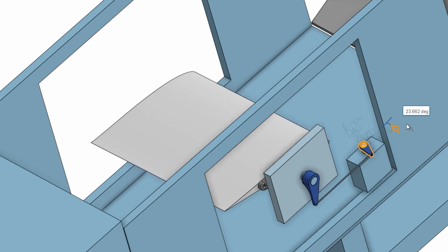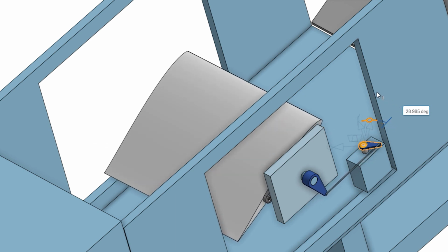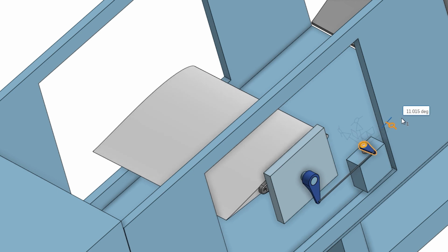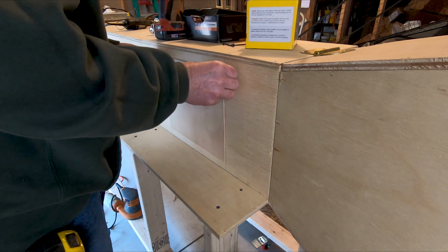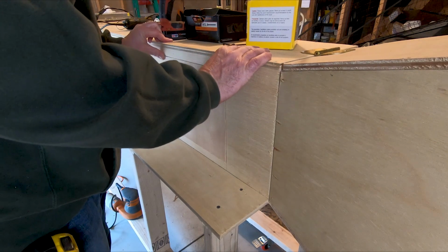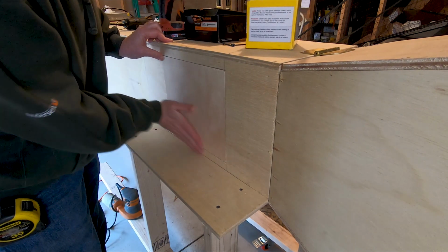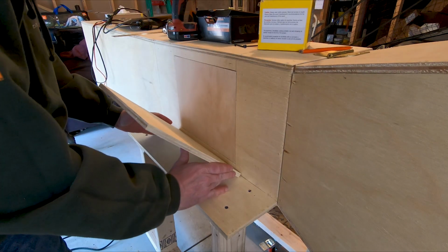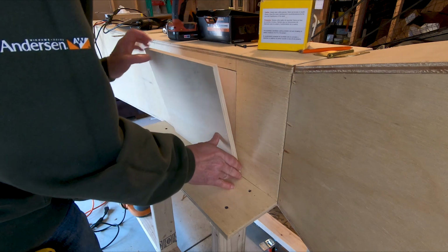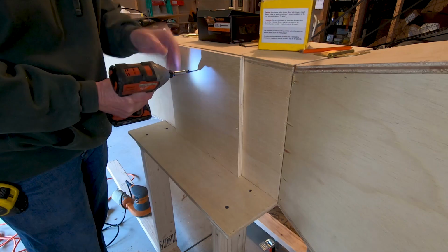And this is what I came up with. I can use a servo mounted on the rear of the door to change the wing's angle. I started by building the rear door panel to fit as tightly as I could. I wanted to make sure it didn't affect the airflow in the test section. I then attached a large panel to keep the inner panel in place.